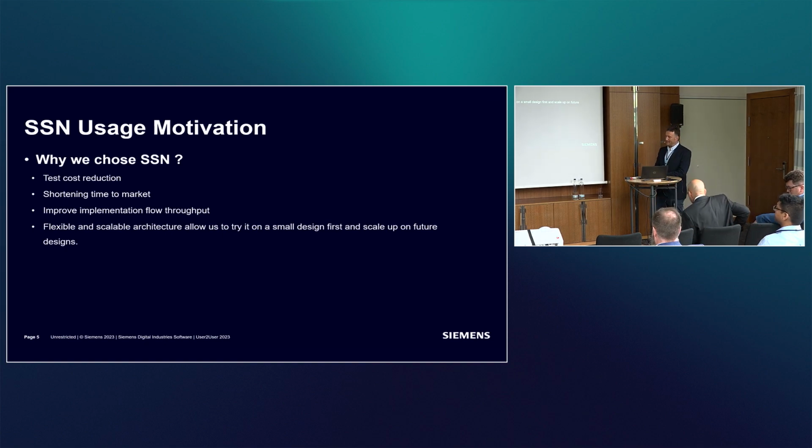Okay, so as Itamar mentioned, our previous mode of work is routing the EDT data, EDT channels, EDT clock, update, and shift clock, and scan enable. Everything is coming from the IO of the package. So instead of that, now everything is going to be handled internally. That's a part of the divide and conquer. So each SSN block generates those signals internally, so we no longer need to handle that, and that is really the key change here, and why we chose that.